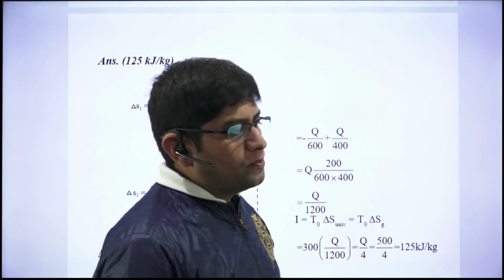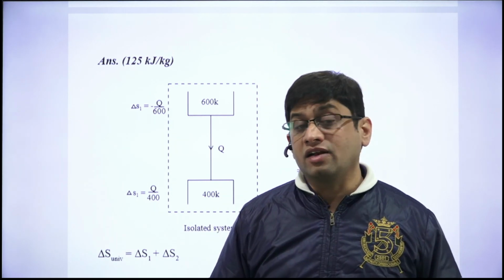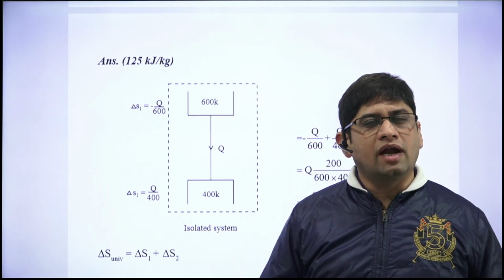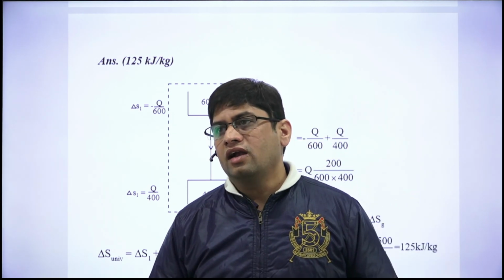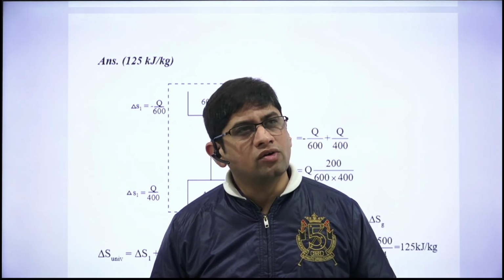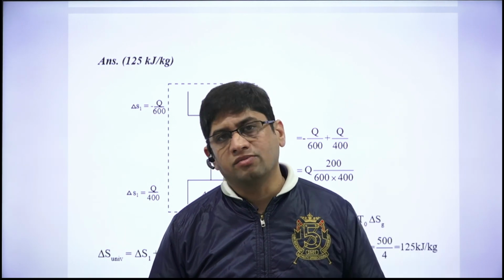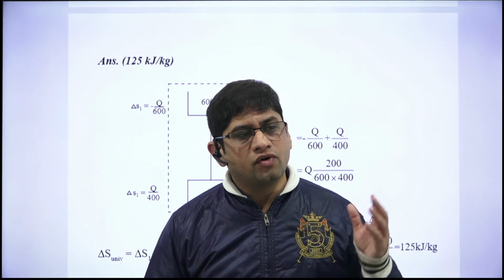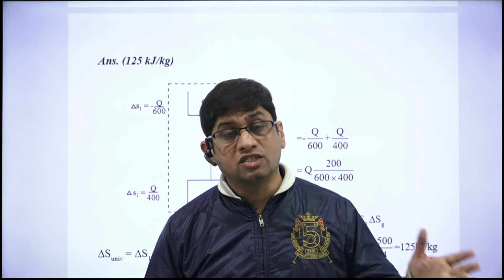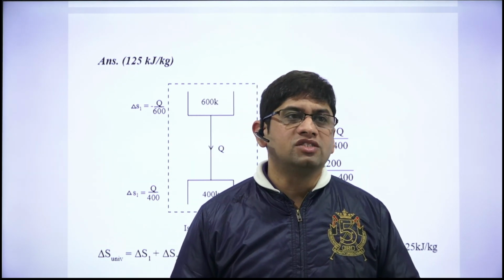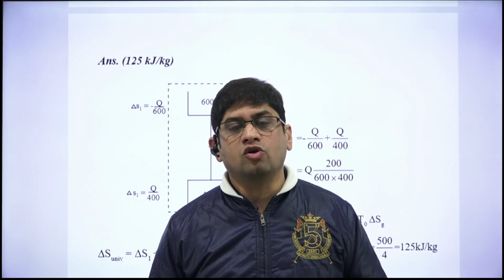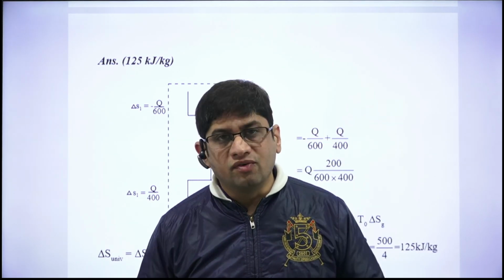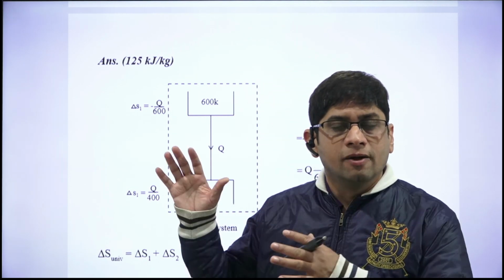In this video of 10 questions, we have done how to calculate entropy change for ideal gases. I gave you 3 formulas. And if the polytropic index is given, how to find out Cn in terms of Cv. And for the throttling process, free expansion, and reservoirs, how to calculate entropy change. Related to entropy change, there is a concept of entropy generation, or entropy change of universe, and hence irreversibility. That is what we have seen in these 10 questions.